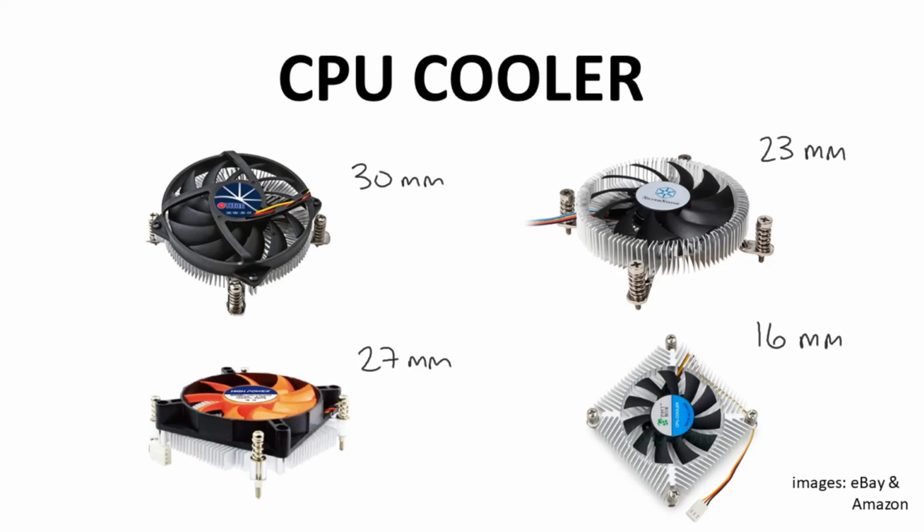Here's another concern. The job of the cooler is not just to fit in the case, but also maintain decent CPU temperatures. These smaller coolers on the right, with their smaller fin stacks, are perhaps less effective at cooling the CPU. So this takes us back to selecting a CPU for a thin build. If you're in a tiny case, you'll probably want to focus on 35 watt CPUs. Most of these low profile coolers claim to handle a 65 watt CPU, but temperatures tend to be quite high, especially when 65 watts is the base power and the CPU then turbos well north of that number.